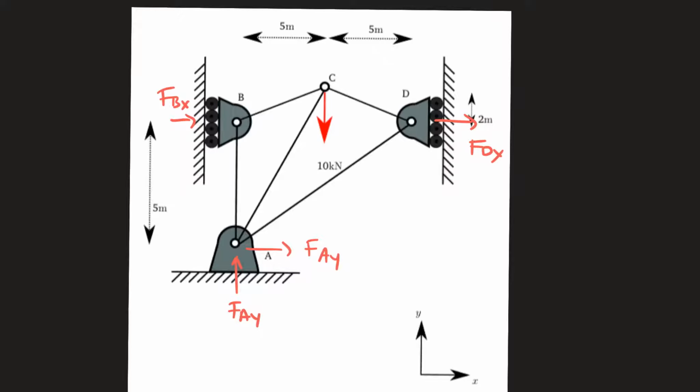So again, we've got more external reactions that we can cope with, more unknown reactions. So for this one, clearly we're going to have to pick another one of these to be a redundant reaction. We're going to remove this one, but then we need to determine the displacement of this, effectively where this whole structure will move in this direction now.